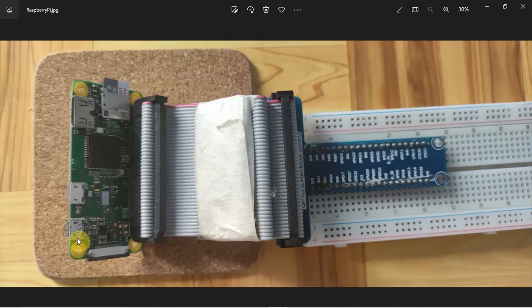mobile phone charger. Just avoid connecting it with your laptop to the USB cable, as the current might not be sufficient enough to power your Raspberry Pi 0, and you might encounter issues when you are programming with your Raspberry Pi 0. And then once the Raspberry Pi 0 is connected to your network, then we'll proceed with finding the IP address that will be assigned by your Wi-Fi network to the Raspberry Pi 0.